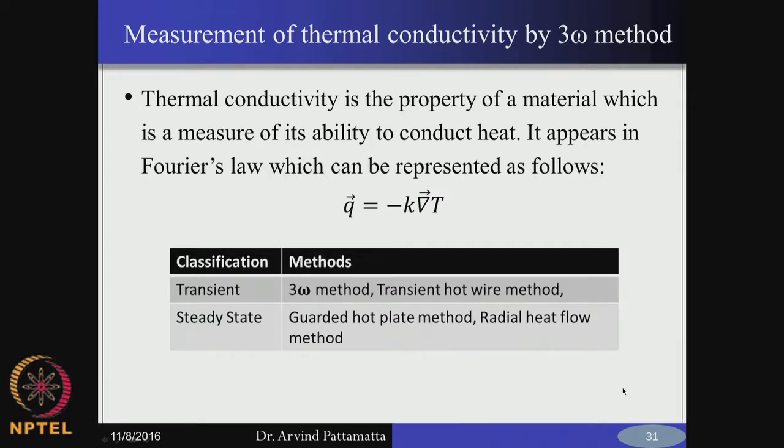So, you have the bulk thermal conductivity, which you use to calculate the relaxation time of the phonons and so on. Then you use the Boltzmann transport equation to find out the effective thermal conductivity at the reduced size. Now, how do we verify this? How do we verify the value of thermal conductivity coming from the solution? You also have to have experimental methods, only then can you verify your theory.